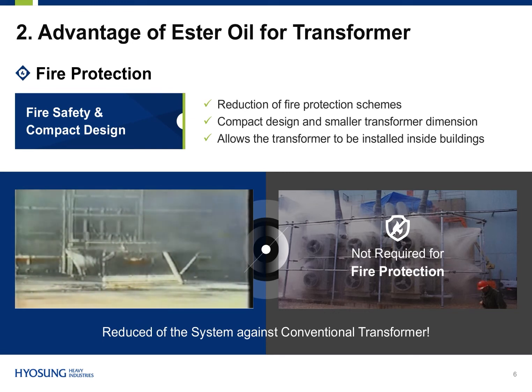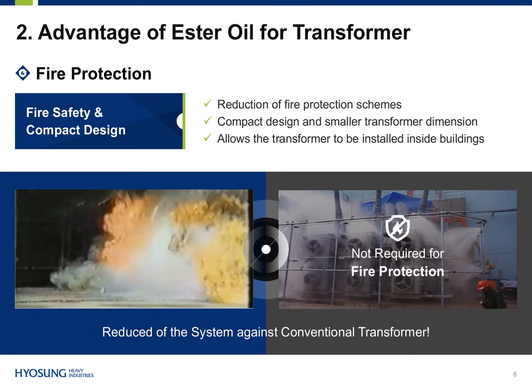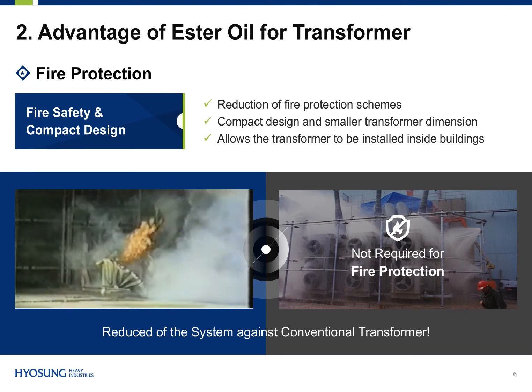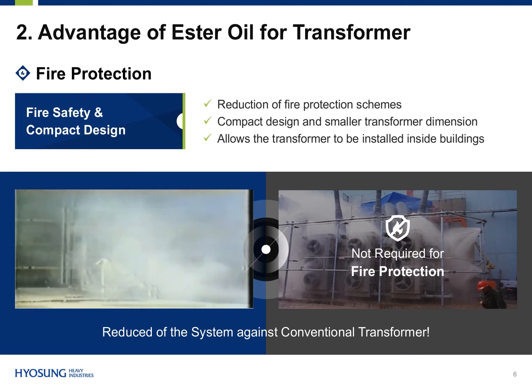Since synthetic Ester Oil has a high fire point and self-extinguishing characteristics, it is possible to reduce fire protection schemes such as firewalls and costly fire protection systems. With Ester Oil insulation, it is possible to install a transformer inside a building, even a residential or commercial building.